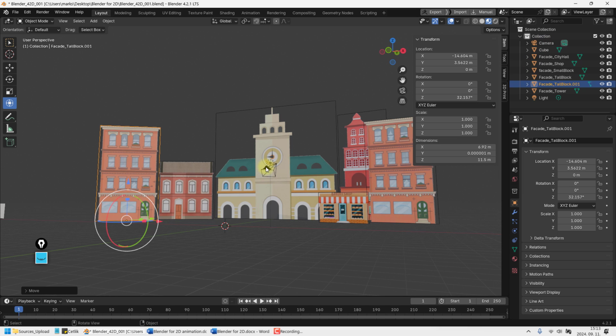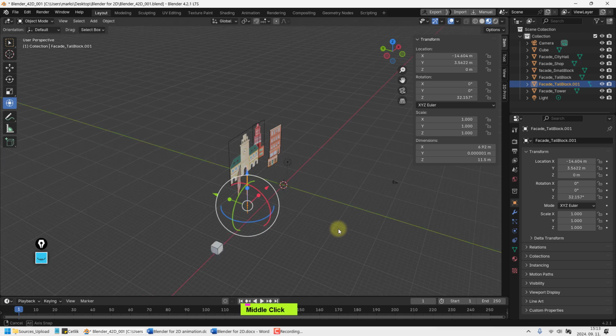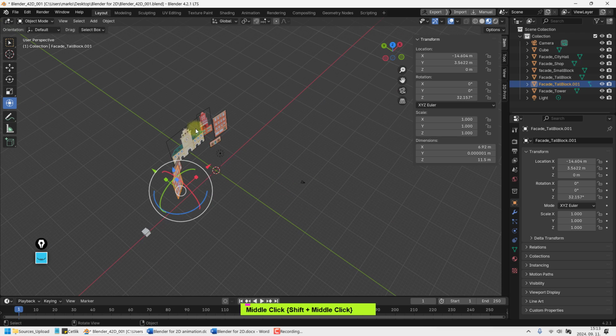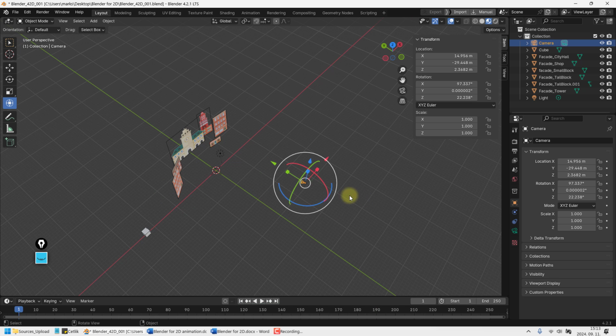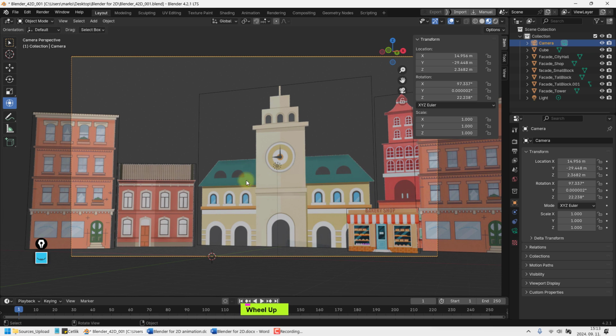So once we have it, the camera itself is active because that's the only one. That's the camera. This little thing indicates that that camera is active. Now, if you have a perspective set and we have an active camera, if you press Ctrl Alt and numpad 0, it will convert your 3D viewport into a camera position. So right now, the previous pose, the virtual viewport camera, is actually replaced with the 3D camera. Okay, so that's nice. We can zoom in. This is what the camera sees.